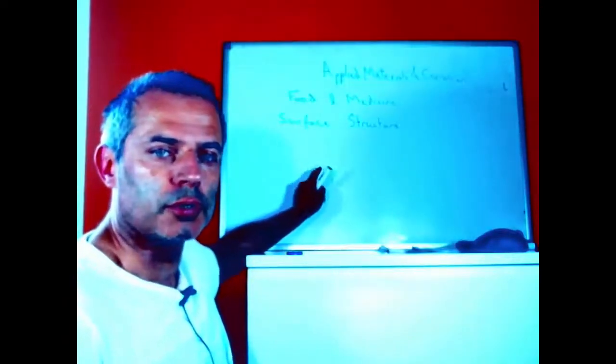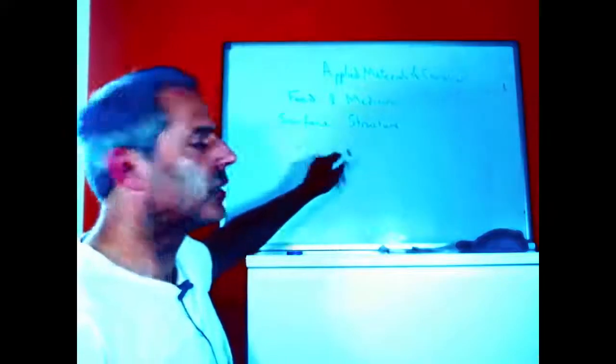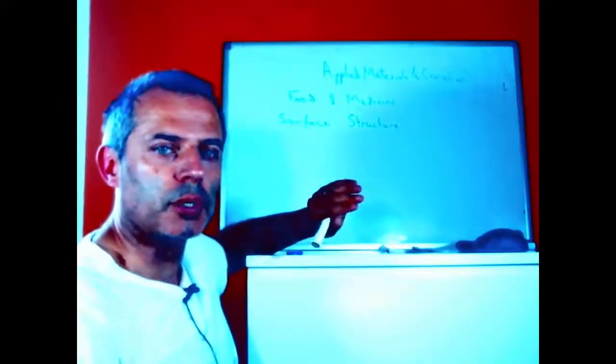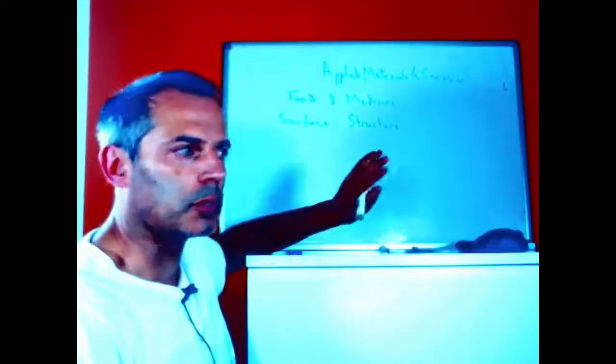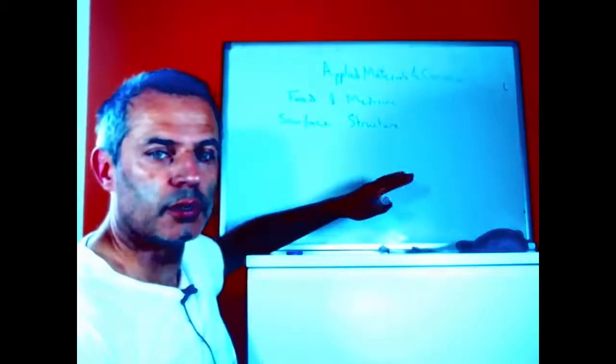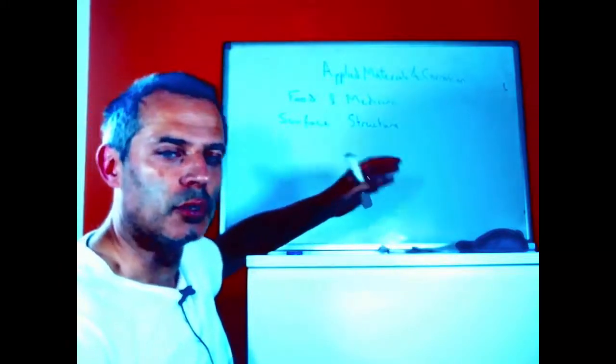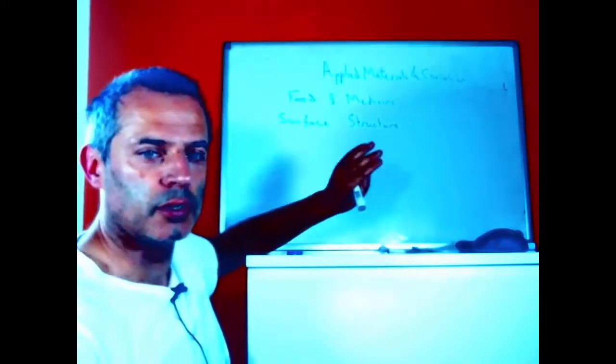If we look at what we would like on the surface of our material to make it less attractive to bacteria, the simplest way to do that is to make it as smooth as possible, because that reduces the amount of crevices where things can hide. And our engineering design part is to not have any hidden holes.